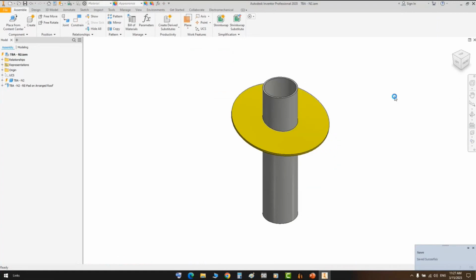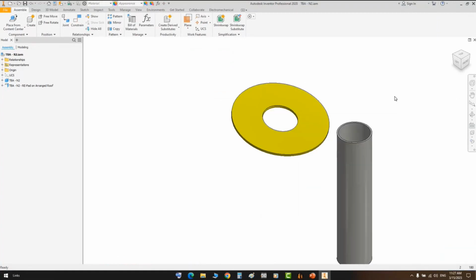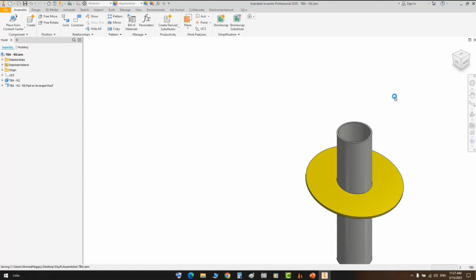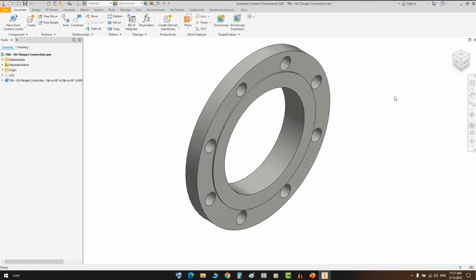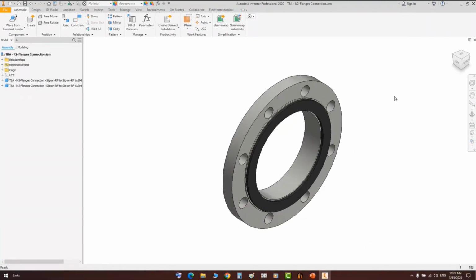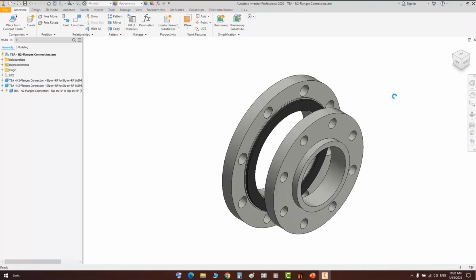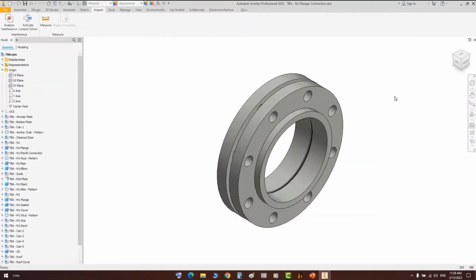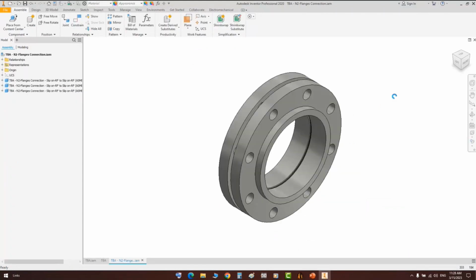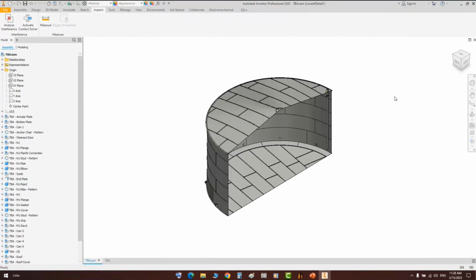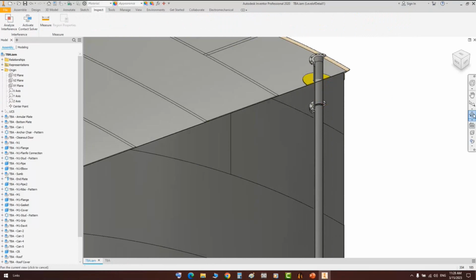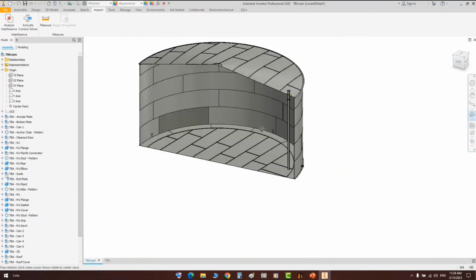To update the nozzle offset from the center line and connect this nozzle with 2 flanges at the inlet. After that, a dip pipe with 6 meters length. In the same way, you can add a stud bolt for this flange, like what we did with the drain pipe. So now we have a pipe with internal projection, like that.